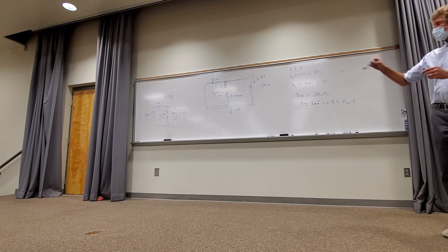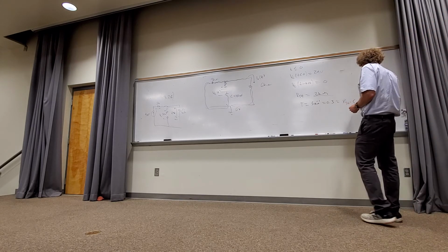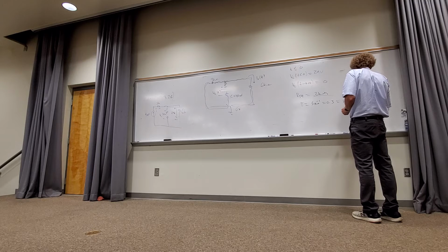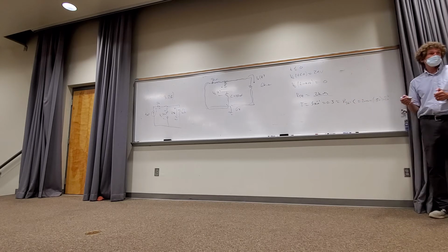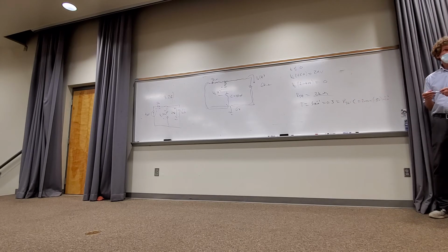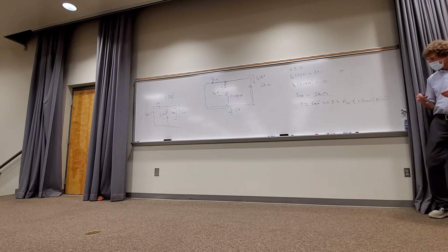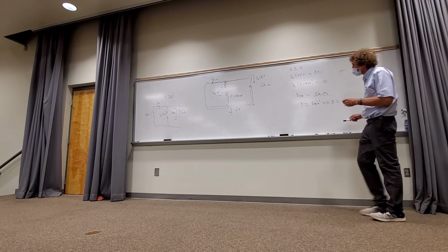All right, so that would be 2,000 times 150 times 10 to the minus 6, if you want to write the whole thing out. You with me? That's all it is. R Thevenin times C is tau. Correct, class?